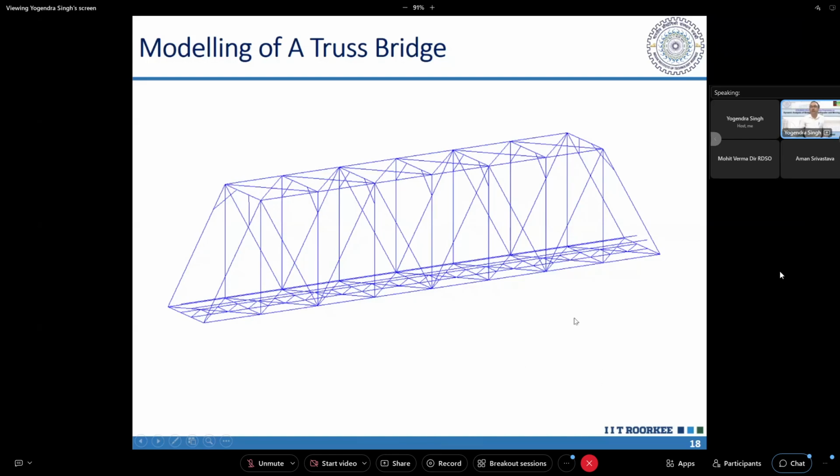So which element we have to use will depend upon the joint condition. So we should look at the type of joints we are proposing. Based on that, it will be decided whether the moment degree of freedom will be there or not, and whether it will be connected rigidly or integrally with a moment connection with the adjacent element.